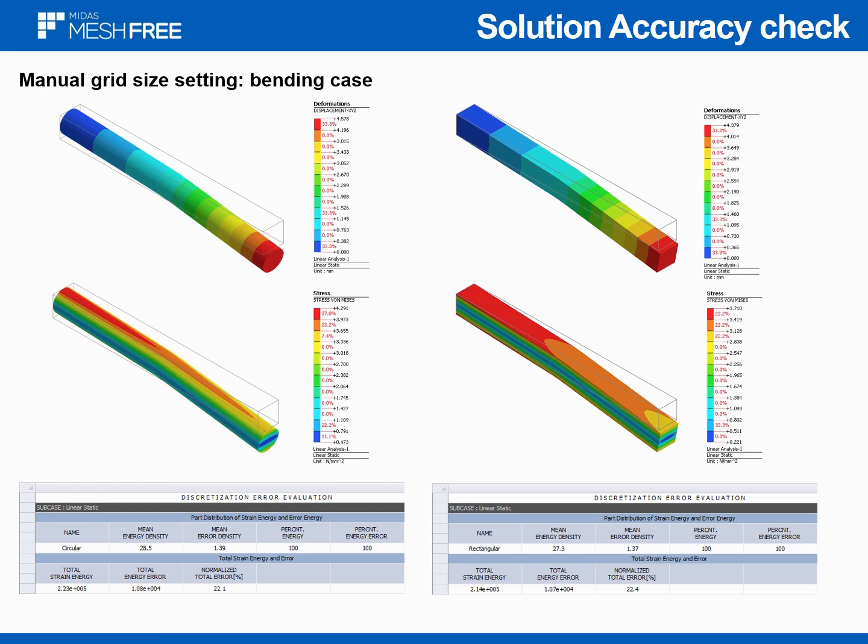So we have to figure out the stress condition inside your specimen. Then we can use one element along some axis, but generally it's not recommended. We don't know which kind of stress will be generated. So I'm just showing you how to set up the model and which size should be avoided. One by one by one is not recommended at all.